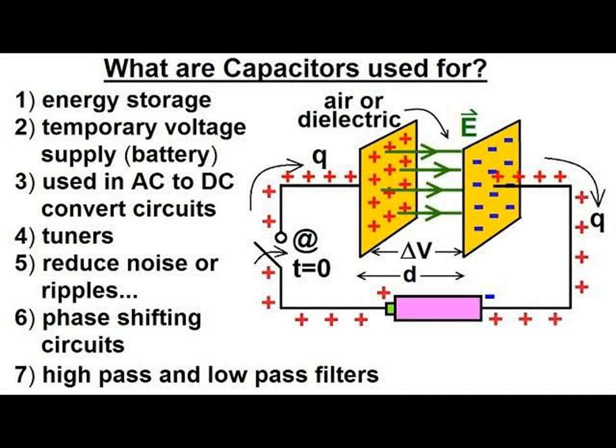You got it? Take note, 1 over C1 plus 1 over C2 can also be written as C1 plus C2 over C1 C2, so C effective is C1 C2 divided by C1 plus C2. But you can't do that for C3, for 3 capacitors, because it is complex.